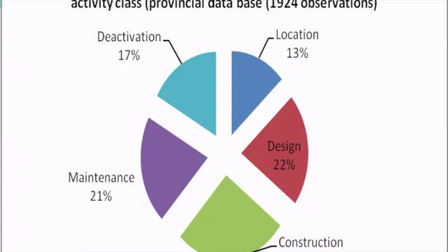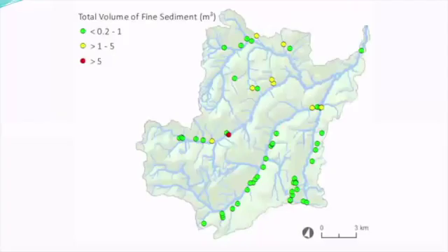In construction, the main thing is to not leave bare surfaces open to erosion anytime you can help it. Where you know you will be generating fine sediments, have a transport route for that storm flow to direct the sediment to travel harmlessly to the forest floor.